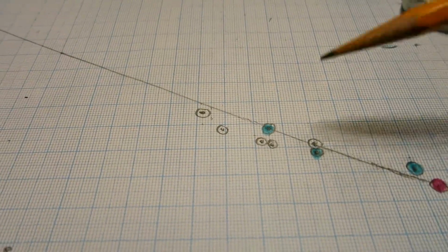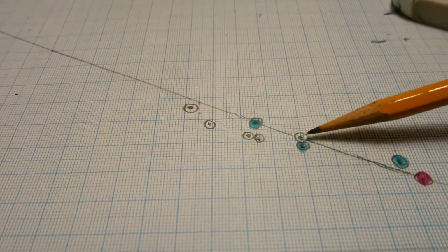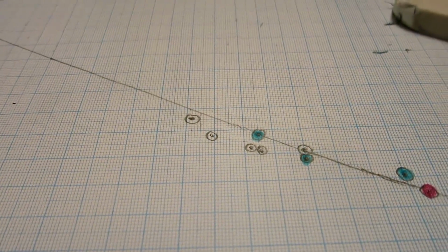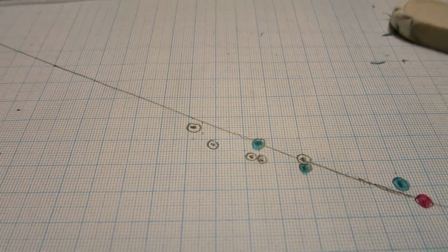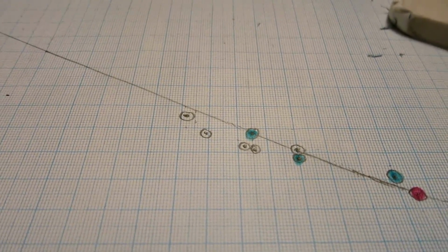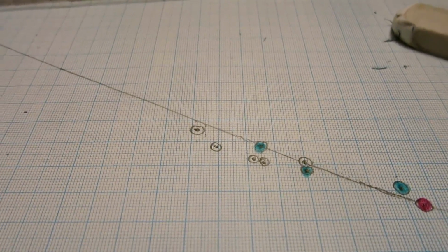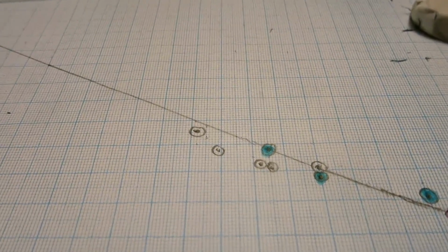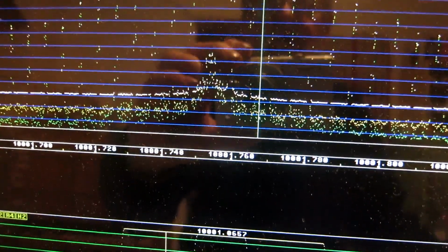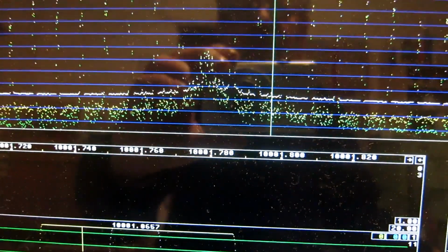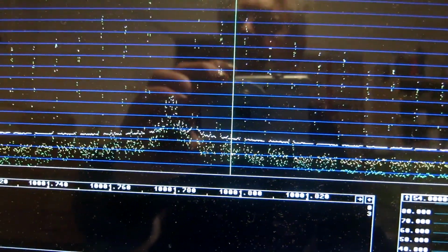And the double precision gives me points here, and I will look with larger resolution because this is close range. I will just continue a little bit further to study what I'm really doing. First, I expand the spectrum, clicking here, in order to see better the structure of the correlation spectrum, the green dots, to see if I can locate spurs in it.